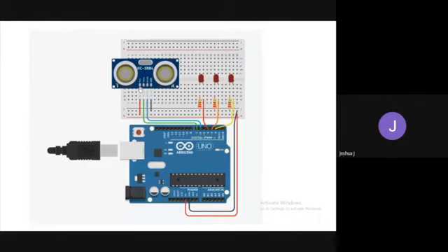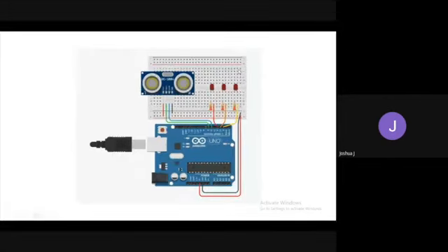Now we will move on to the next. So this is the basic hardware setup. Now I am connecting pin number 7 to the trigger. If I want to trigger this transmitter, I have to send logic 0, logic 1, logic 0, like that. I have to make this pin high and low, the same way we turned on and off the LED.